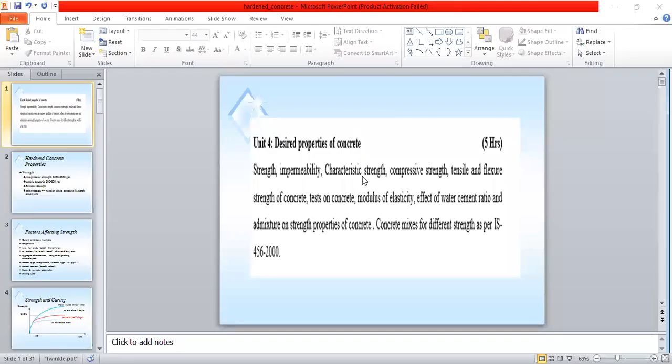So with that, you are going to measure the flexural strength of the concrete by putting in the formula PL divided by BD square. Okay, PL divided by BD square. Understand the flexural strength of the concrete. Everyone has understood? Yes, sir.